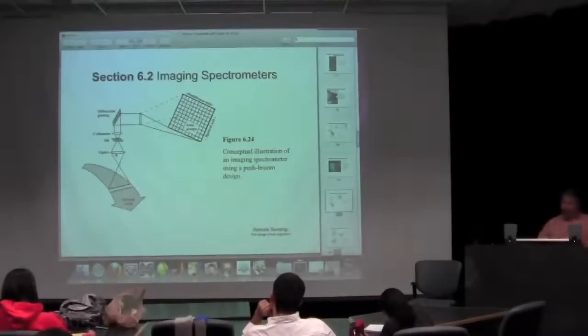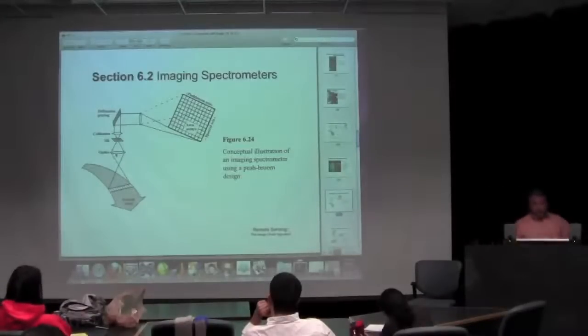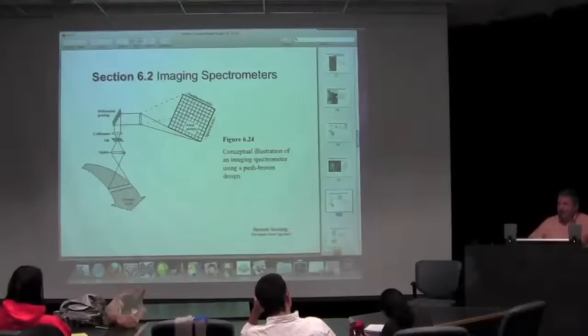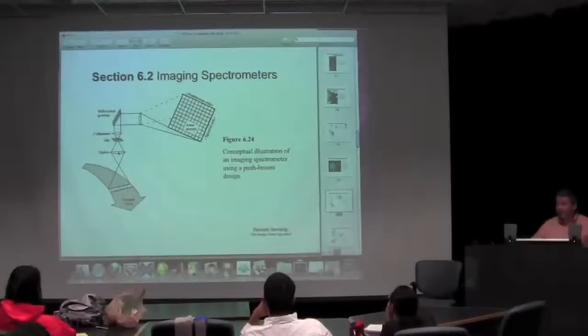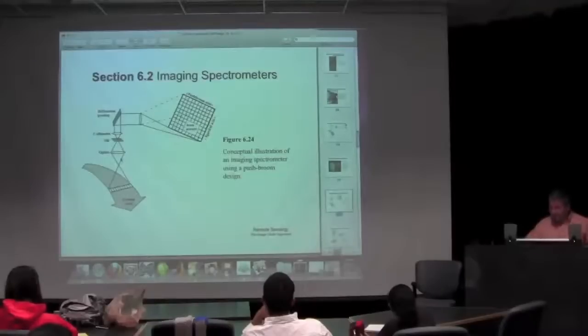So it's going to pass energy from here to here. So in this case, you want to be very generous in your optical design, in the sense that you want to use an oversized optic so that the projection of the slit through that optical system stays as close as possible to the center of that optical system. You don't want to start to get the geometric distortions and the quality distortions that you'll tend to get near the edges of an optical element, whether it be a mirror.